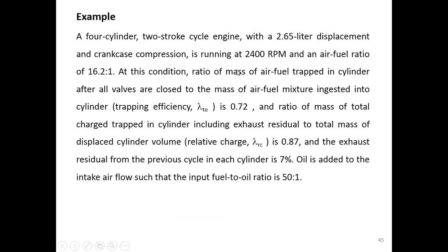The first mass is the mass of the air fuel trapped in the cylinder after all valves are closed. That means both the intake and the exhaust valve are closed. This is the mass of the air fuel that is trapped in the cylinder, compared to the mass of the air fuel mixture injected into the cylinder.